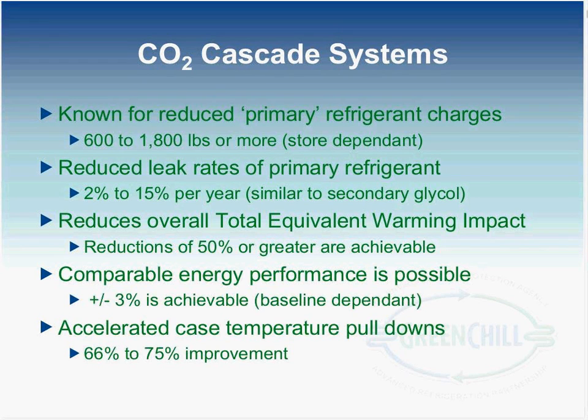Another benefit for using CO2 is reducing the primary refrigerant leak rate. Studies done by Arthur D. Little and others have shown refrigerant leak rates in the 2 to 15% per year are achievable. And again, this is a close coupled system, so we would expect similar or better results with a cascade system as you would with a secondary type system.